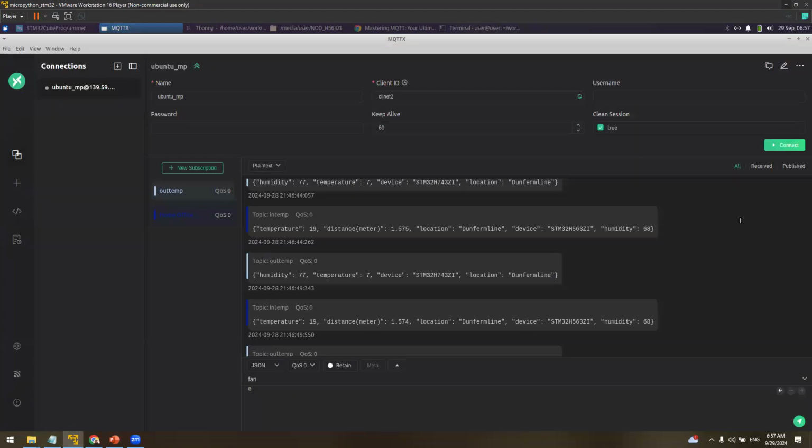So I'm just opening my app. This can be controlled via our mobile app as well. If you have any MQTT app, you can control these devices, because we are using the protocol called MQTT. And at this moment, whatever we have done is all over an unsecure line. It's not secure at all. We have not implemented SSL yet. It's all very much open, and anyone who knows our IP can control the data and can monitor the data.